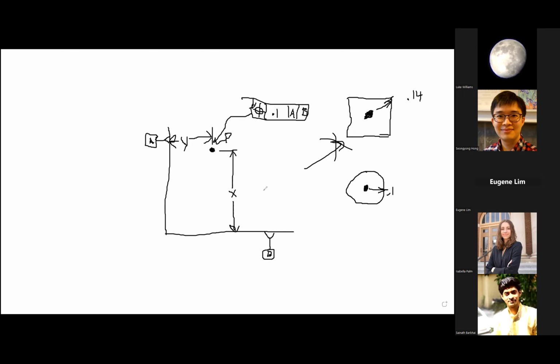It's much more specific because instead of allowing a box, as we see on the top here, instead of allowing this point to meander to the corners of this box and move way out of the way, for example, if this was like a hole, if it moves 0.14, that probably would be too much movement in this design, let's say.